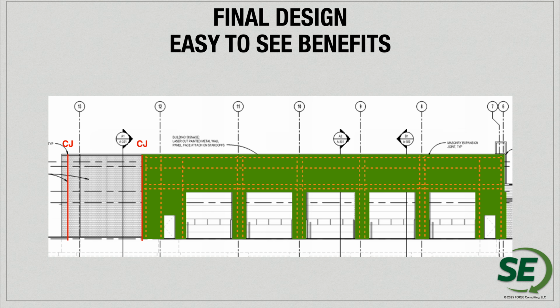So what I have highlighted here in green are areas where we do not need to put control joints in the masonry elevation. But then maybe the rest of the building has standard block walls. We have rectangular walls where we can go back to light horizontal reinforcement and control joint spacing around 25'4", plus or minus, depending on height of the wall and support conditions.